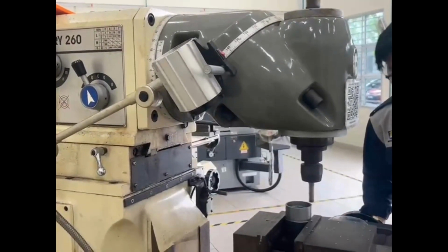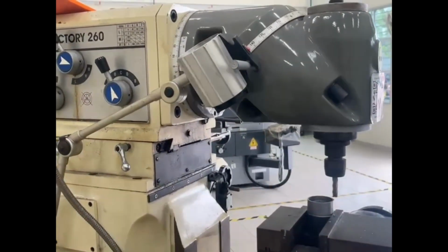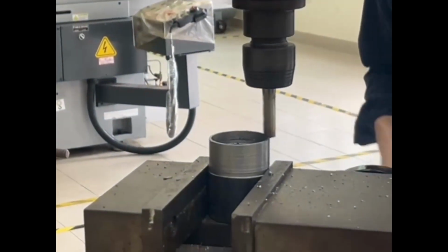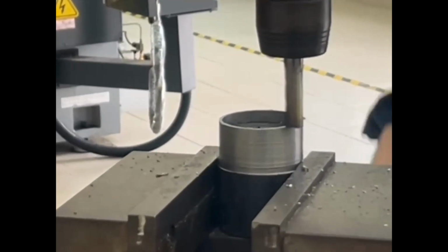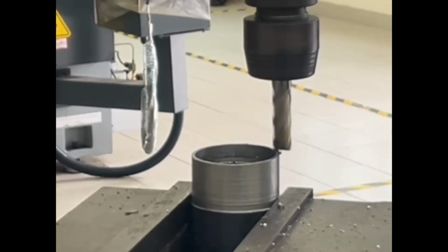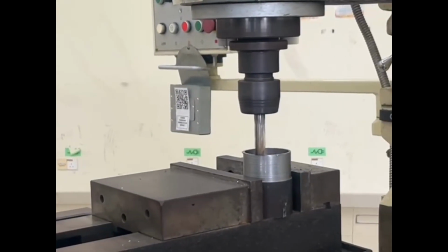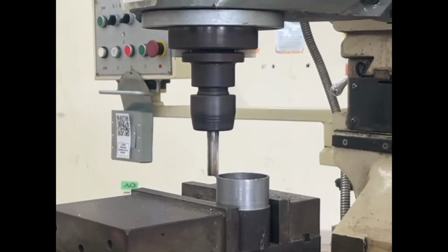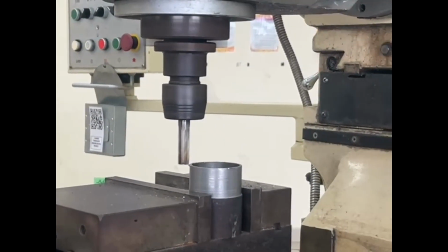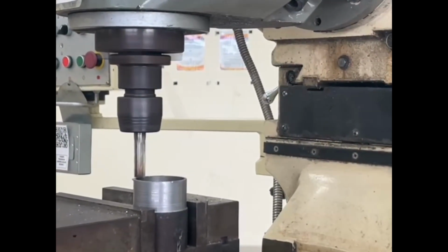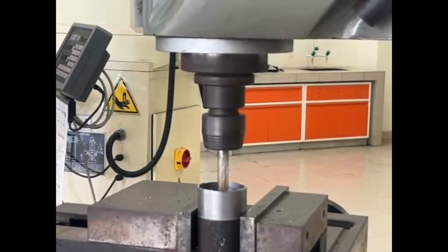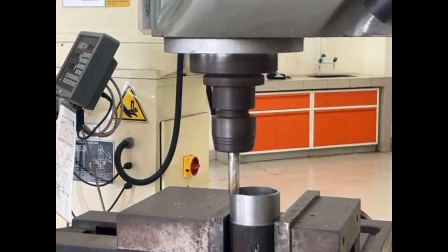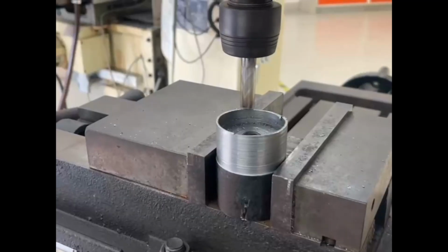Then, the process of milling is executed. In this project, however, milling is used on part 1 to remove additional length of the workpiece. The milling process is executed by removing the top surface of the workpiece in increments of 1 mm. After the milling process, we can finally get the accurate and precise dimensions of the workpiece.